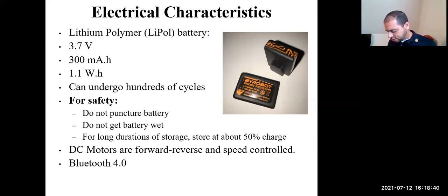So, by the way, look at the rotors. These are the directional rotors, as you see here. If you want to replace a rotor, you cannot just replace any rotor anywhere. You have to pay attention to the direction. As you see here, if you look at it carefully, two of them are right-handed, the other two are left-handed. So these are the electrical features.